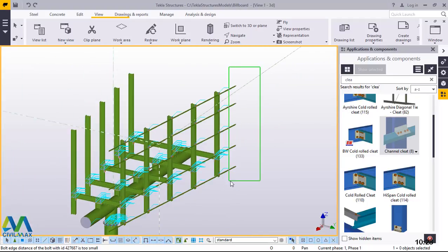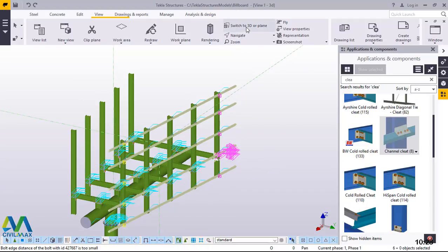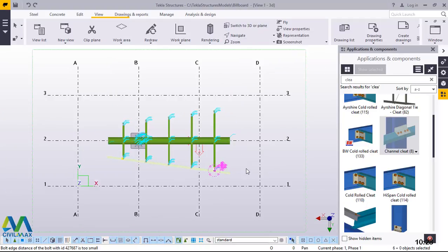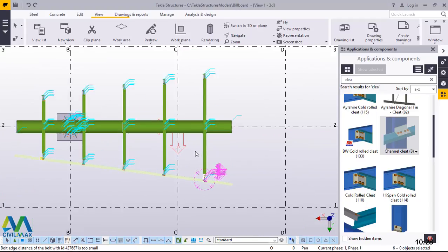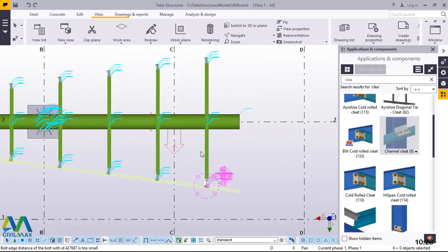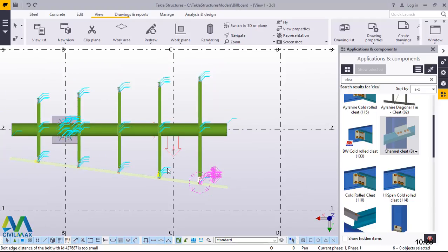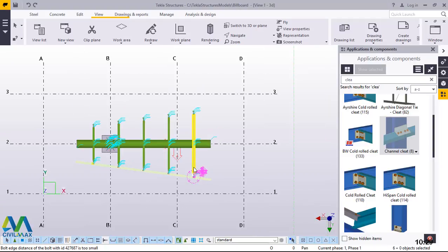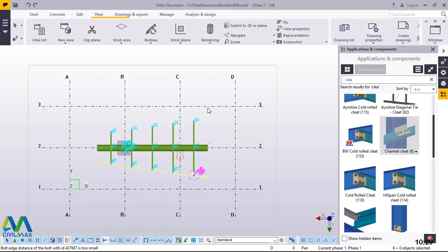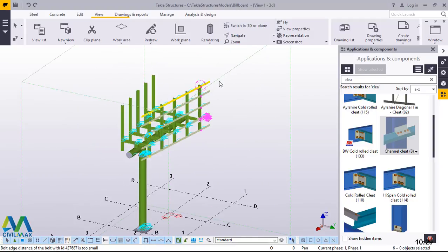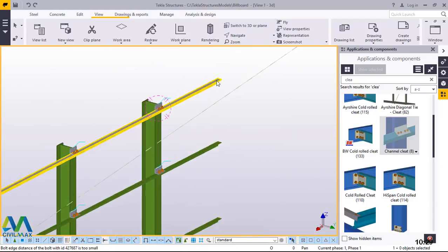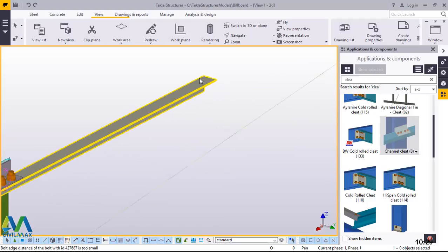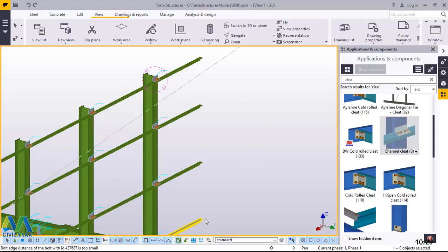Now just select all this, then switch back to the plan view. First of all, make sure the XYZ plane is positioned on a global position, or on a default position, and then we want to mirror this to the other end. And prior to doing the mirroring, we first of all come back and click on empty screen. We want to connect this all the way to the bottom end here.